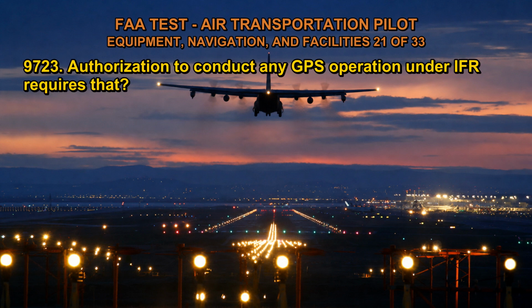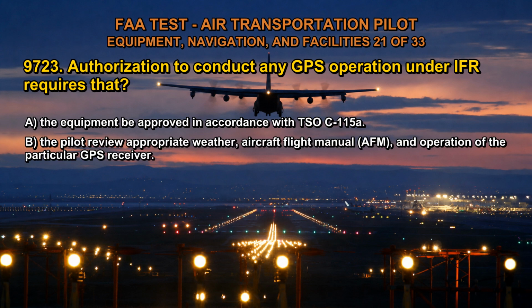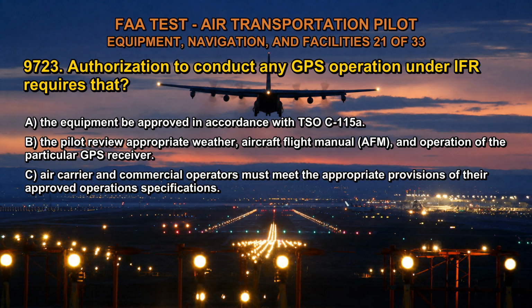9723. Authorization to conduct any GPS operation under IFR requires that A. The equipment be approved in accordance with TSO C115A. B. The pilot review appropriate weather, aircraft flight manual, AFM, and operation of the particular GPS receiver. C. Air carrier and commercial operators must meet the appropriate provisions of their approved operation specifications.